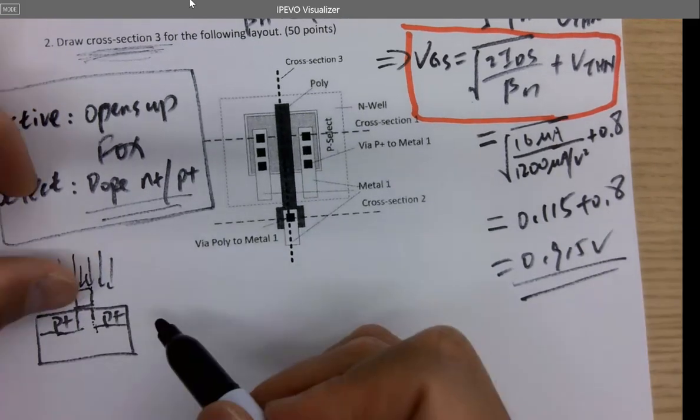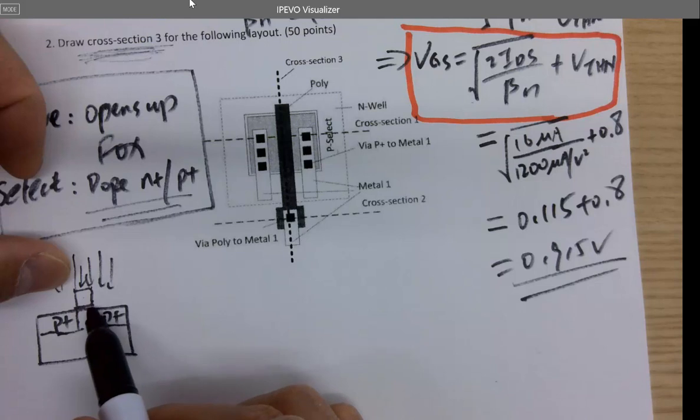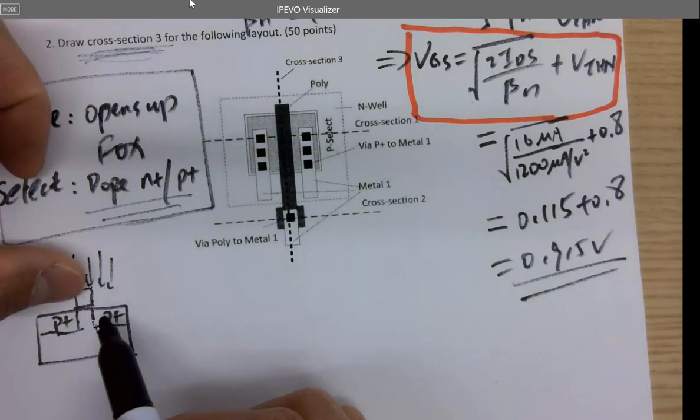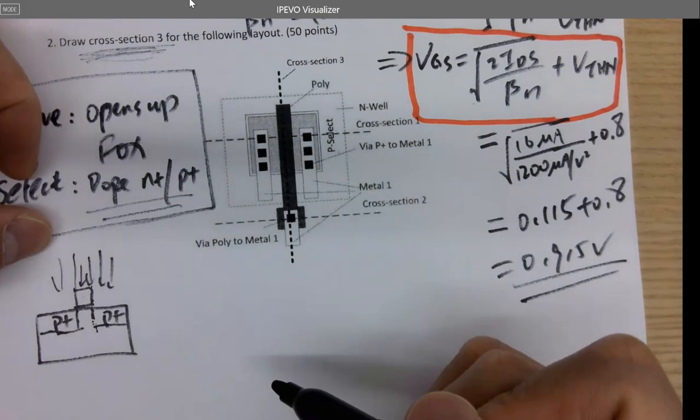You don't have to dope this first and then place a gate on top. There's no way to do that because these are nanometer scale. There's no way that you can make it accurate. So I have to put a gate here first, then dope it.